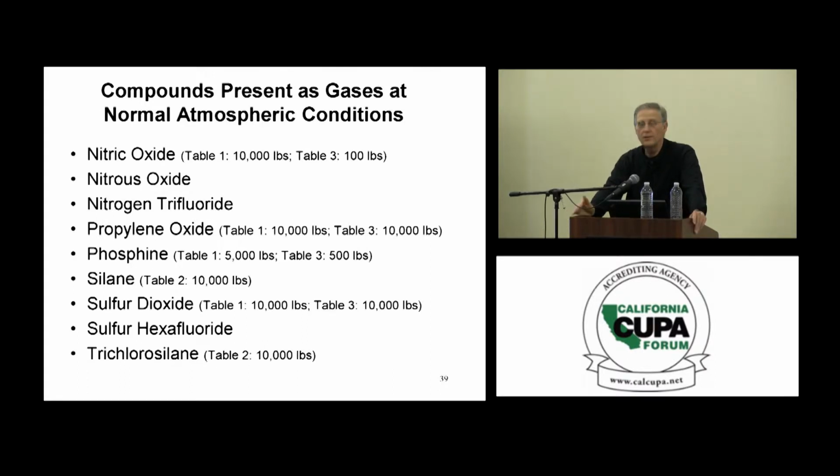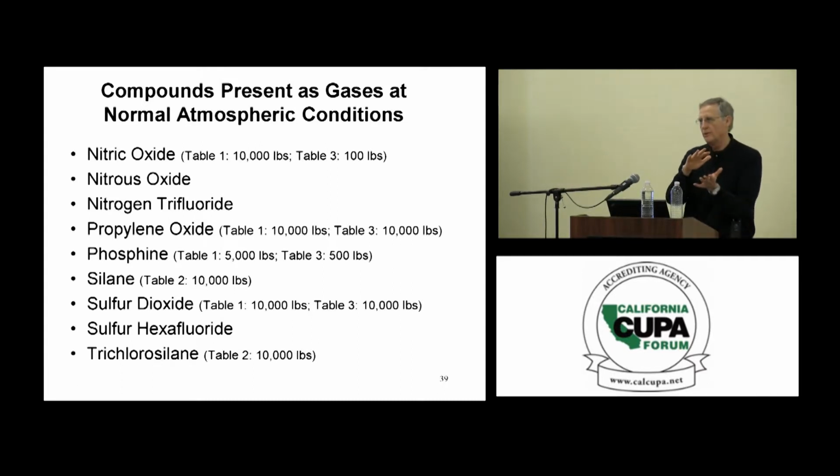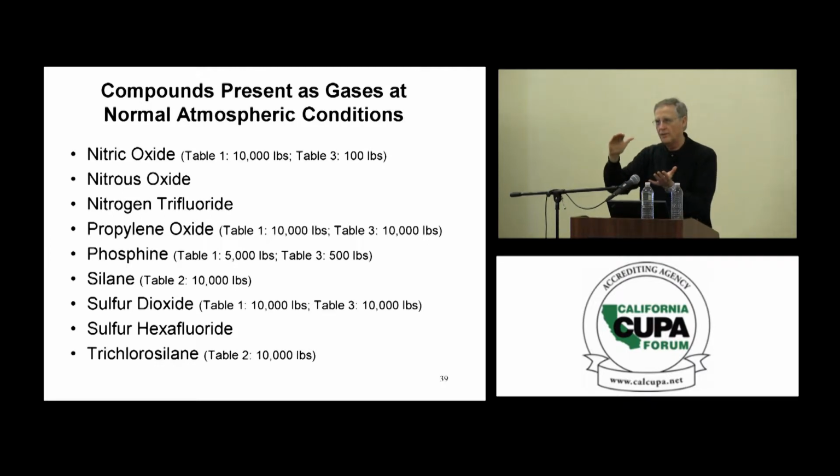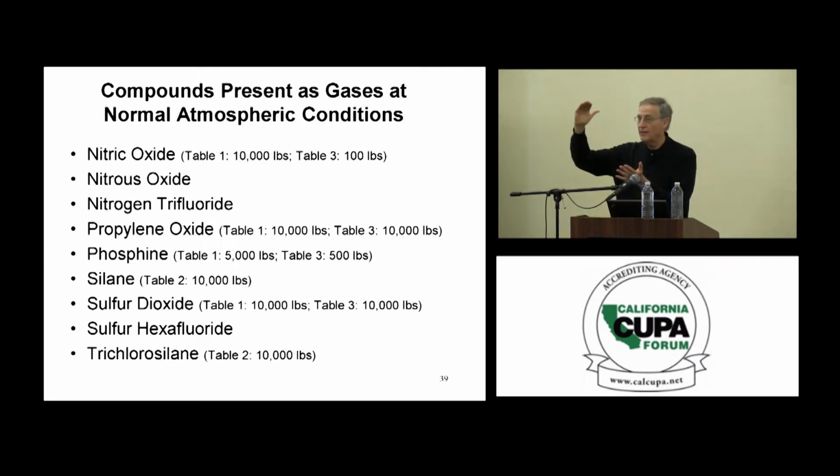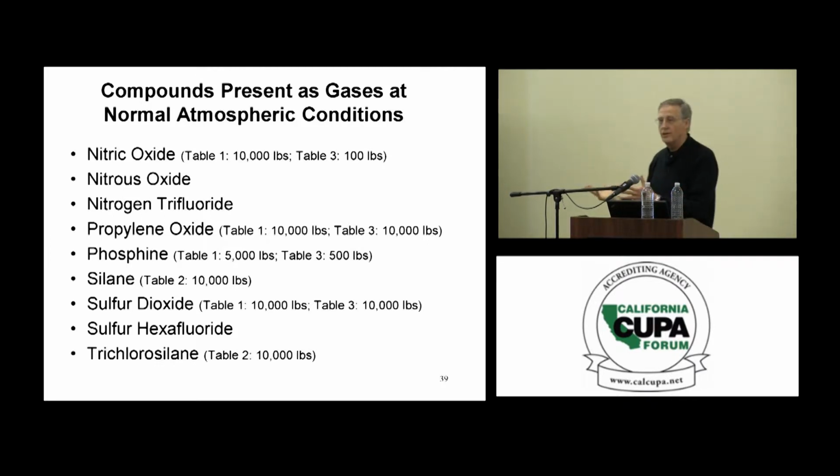And are those important? Absolutely, they're important. But what happened to all of the process safety excursions, when for some reason we got outside the operating envelope we were supposed to be in and we got high level alarms? We didn't get up to high-high alarms. Those aren't in there.